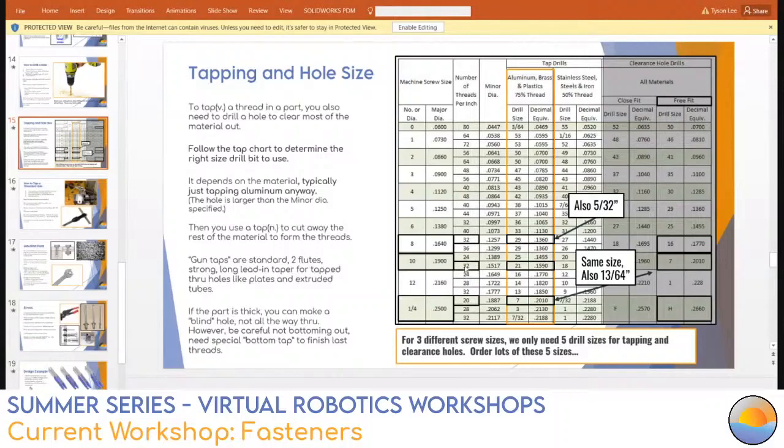This gets into a much larger, much more technical definition of why and how in terms of strength. Honestly, if you're going larger than a quarter inch, you probably want to start looking into the coarser threads. That's why I would recommend a quarter 20. It is a lot more common than a quarter 28. Not that the quarter 28 is impossible to use, but the tap size of a quarter 20 is a lot easier to use than the tap size of a quarter 28. It's really too extra fine. When the threads get really fine for being large, you kind of want to avoid those fine threads.